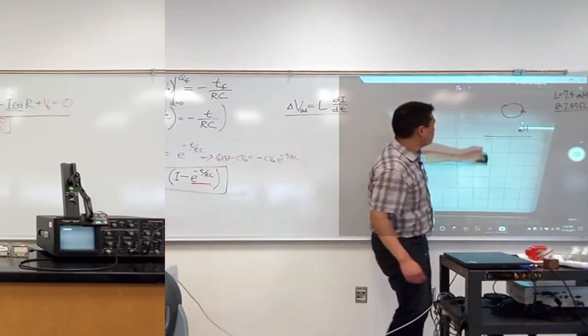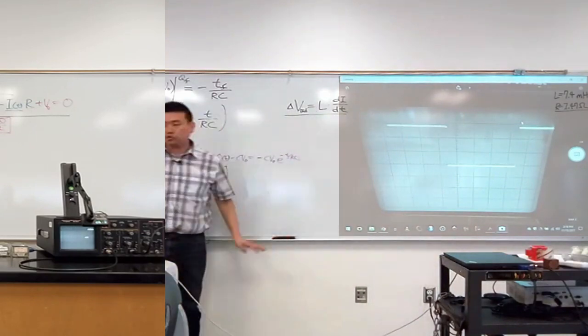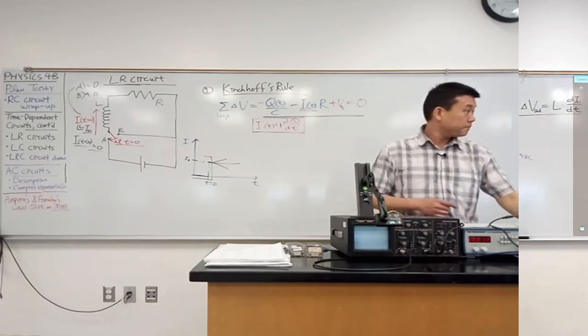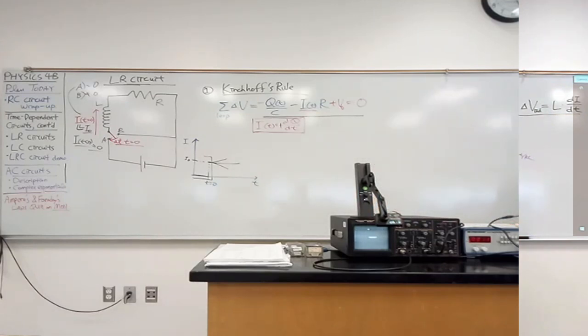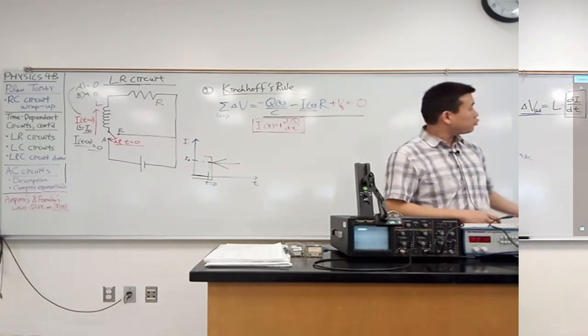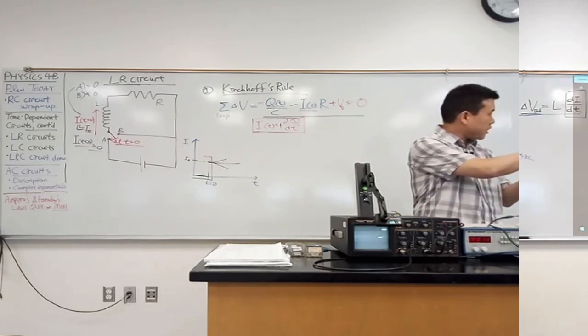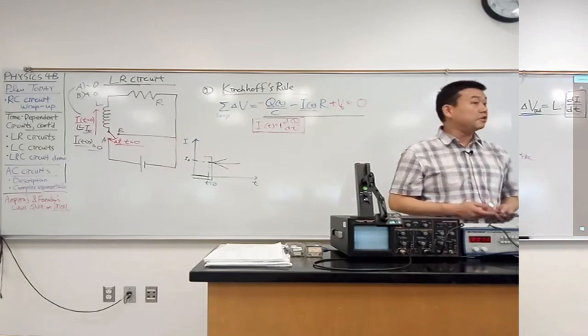But what you may have to look at in more detail is how current depends on time. Yes, that is an important thing: this voltage here is proportional to the rate of change of current, not the current itself. If it was proportional to current itself, I would have no trouble with that kind of current change. So when you have this kind of change in current, how does that cause difficulty when you have an inductor in the circuit?